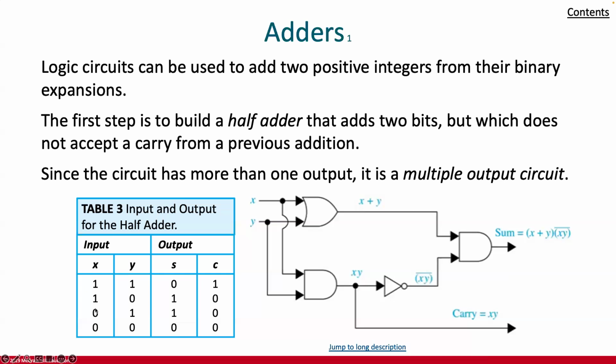If you only have one of them as 1, then the output is 1. And if you have a 0 on both, then both the output and the carryover are 0. So you need to compute the different ways that you can get a carryover. And thus we can see that we have the logic for creating a half adder.